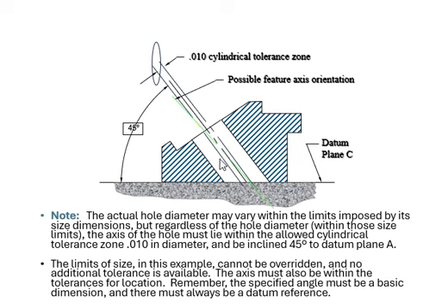If you have a parallel zone, then you are dealing with only a single surface from this view. Be careful when you read what kind of tolerance zone it is, the parallel one or the cylindrical one. You have seen two different examples right now. Of course, this one is outside of that zone, so that's not very good.